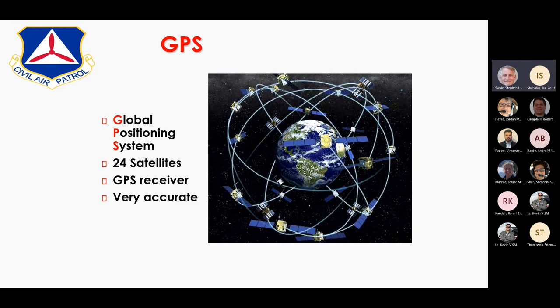And when you go the other direction, you'll be doing 100 knots. We want 90 knots of ground speed so that we get a more consistent search. And by looking at that ground speed and bringing it into your scan, then you'll be a much more precise pilot executing the search pattern that you've selected.